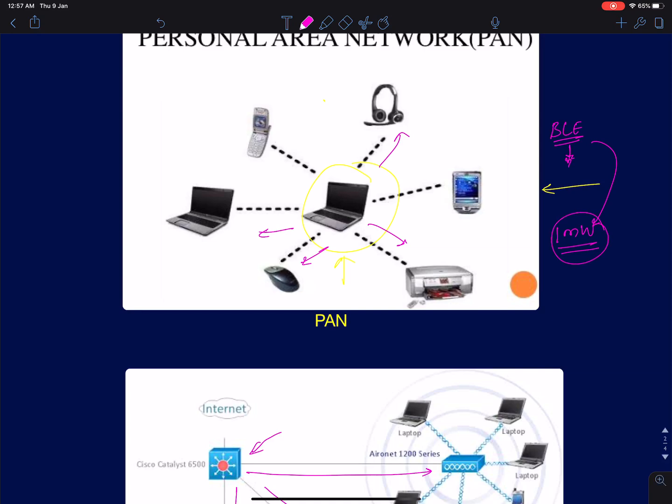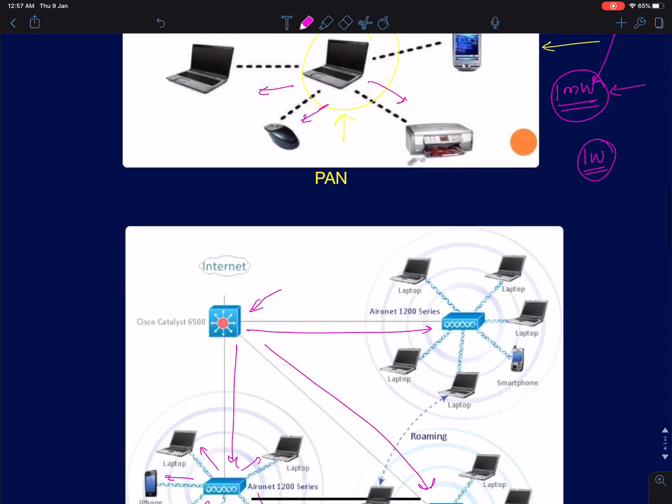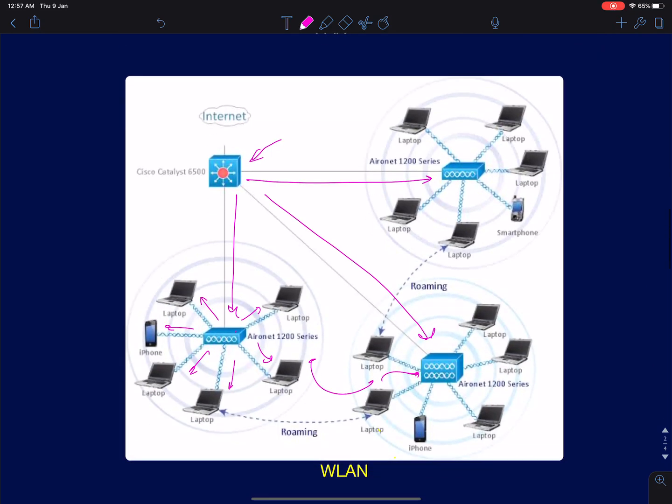Your cell phone, on the other hand, transmits 1 watt of power. So if you are keeping your cell phone very close to your ear, the power amplifier is actually transmitting 1 watt of power. For longer calls you might feel hot around your ear. So if you have a Bluetooth headset, go for it, because it's going to transmit less RF power, 1 milliwatt. In case of wireless LAN, the power levels are of the order of 100 milliwatts. This is for the 2.4 gigahertz range.